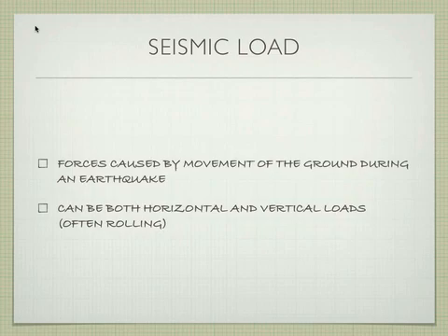Anybody ever been in a skyscraper during an earthquake? No? It's a wild experience, because the floors will actually sway, because they're designed to bend a little bit and flex. If they were perfectly rigid, you'd have the risk of something breaking, and so we'd rather have it flex a little bit. The same thing happens in a smaller building, but in your house, you don't have steel, you're not going to flex like that. You're just going to feel the shake.